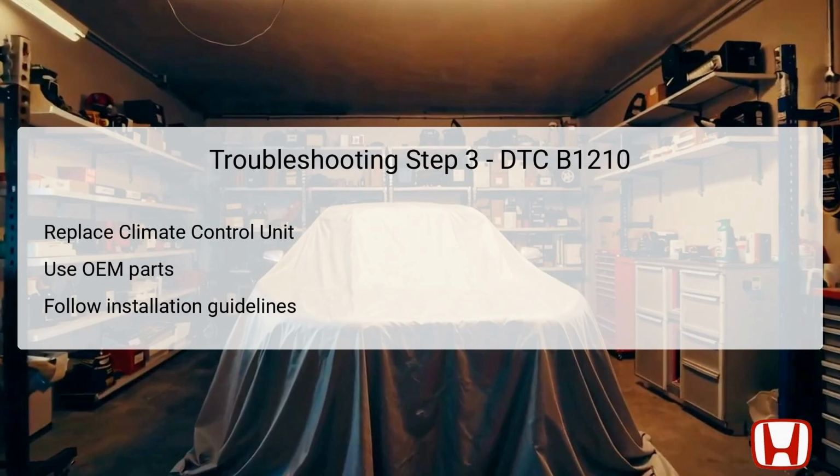Once installed, the technician should clear the DTC using the vehicle's diagnostic tool to reset the system and observe if the malfunction persists. Properly diagnosing the issue and replacing the unit assures the restoration of effective climate control functionality.